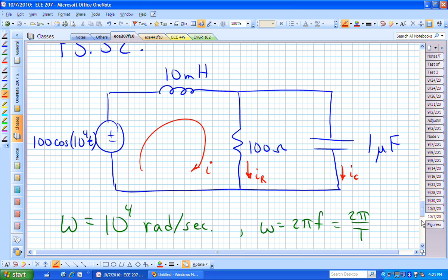What influences the transient? Well, that is influenced by the way this circuit is built and the resistance. But if we have resistors in there, we're going to have transients that will decay. And they'll probably decay pretty quickly in an electrical circuit. After 5 time constants, we've basically reached steady state.